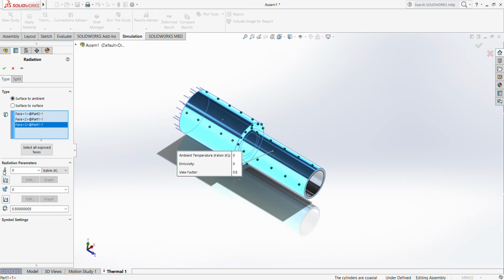Now we're going to need to put a temperature of the ambient, and we'll leave this in Kelvin, because this is cold space. And what I do is I'm going to put 80 Kelvin because space is actually closer to 0 Kelvin. You can put 0. Some people put 3 Kelvin as more of a representation of cold space. 80 Kelvin is what we would do if we put this in an environmental chamber and wanted to recreate the coldness of space. We actually have a chamber that we run liquid nitrogen in, and the walls of the shroud inside this chamber are pretty close to 80 Kelvin.